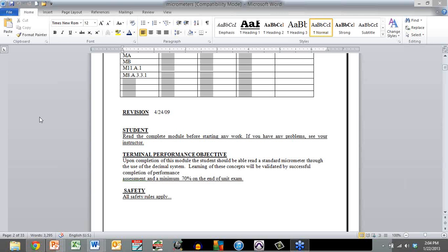Once we get a good feel that pretty much everybody is on board reading it properly, we'll have some setups right in the classroom where they'll have to actually use different micrometers, under an inch, over an inch, moving the number to the left of the decimal or to the right. Once we get them feeling good about that, then we have workstations set up out in the lab area. Each workbench would have different types of components.